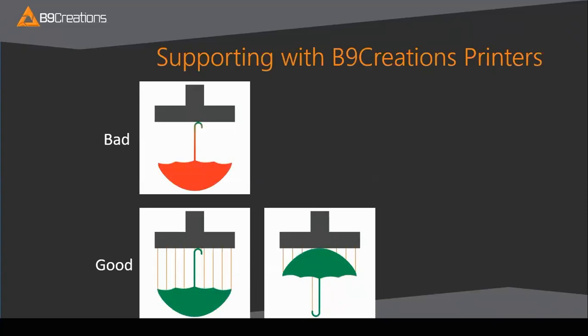The next graphic shows an umbrella upright on the build table. This will help to understand where to place supports on the model. While keeping the contour lines in mind from the support software, think about water running over this umbrella. Where is the water going to fall from as it hits and flows from the top of the umbrella to the edges here? The answer is the very tips of the underside here.